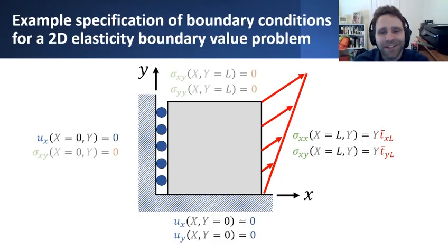On the top face, it's a free surface. I'm not imposing any load there, but I still have to prescribe the components of traction that are exposed on that top face. Those being sigma yy, the normal component of stress exposed on that top face, and sigma xy, the shear component of traction exposed on that top face. Both of those being equal to 0.